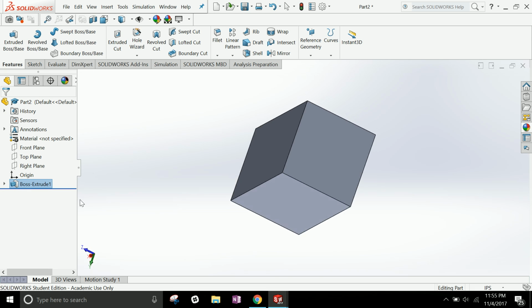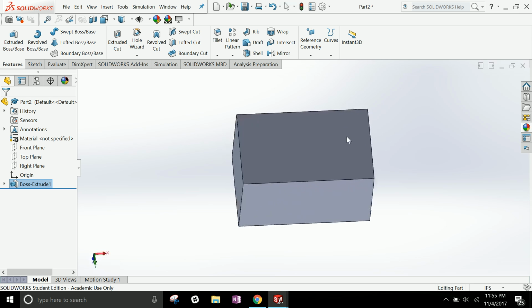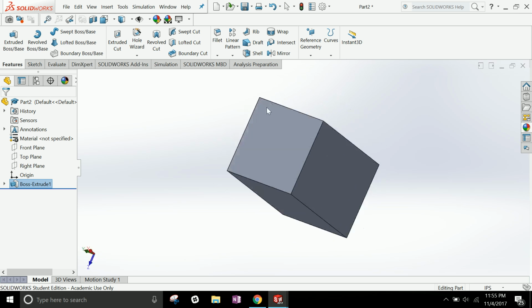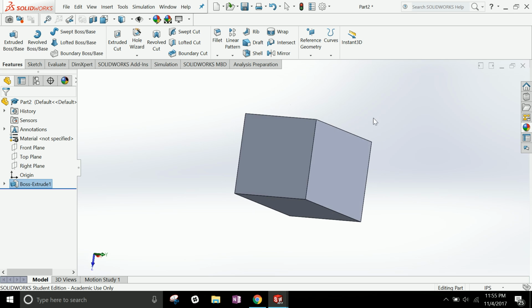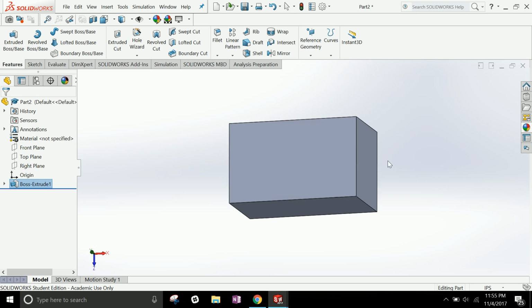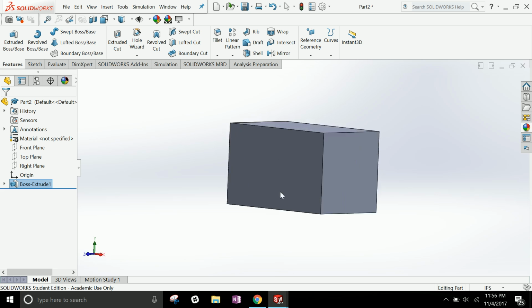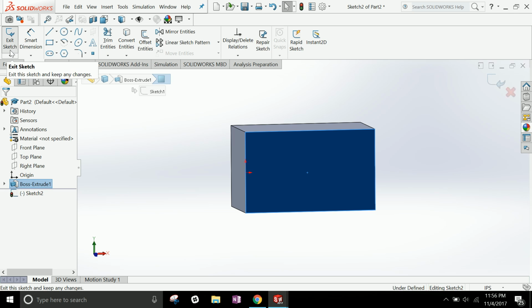What I've done is I've now created this 3D model, and I'm simply using my mouse right now to go ahead and spin it in every which way, every direction. And now we can continue to modify in the same way. So let's say I don't want this to be a simple rectangular prism. Maybe I want it to look like steps, okay? What I can do is click on any surface and go back to sketch and create a new sketch.